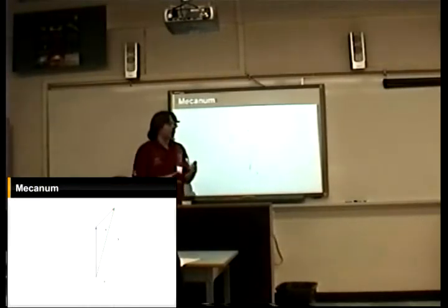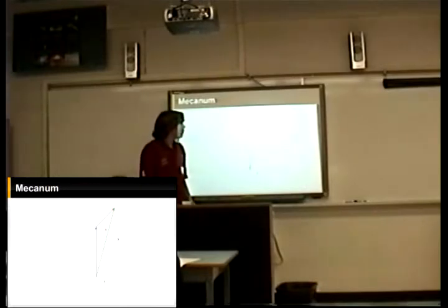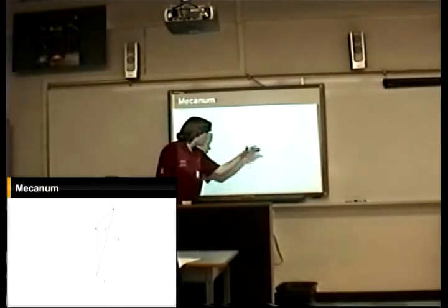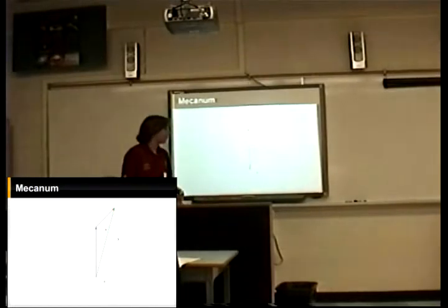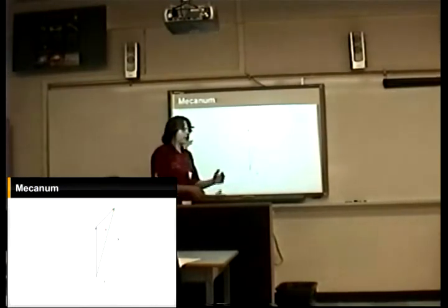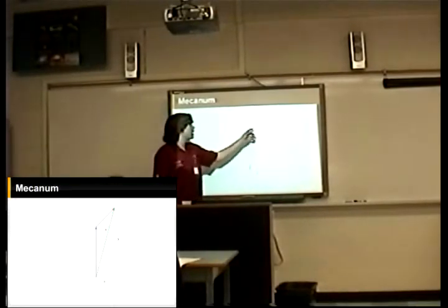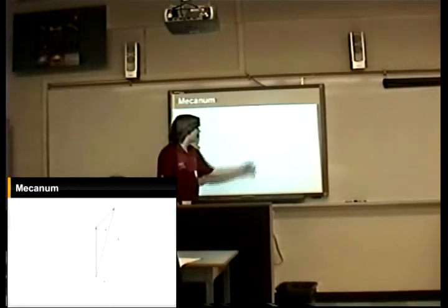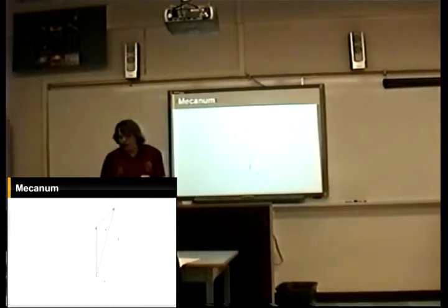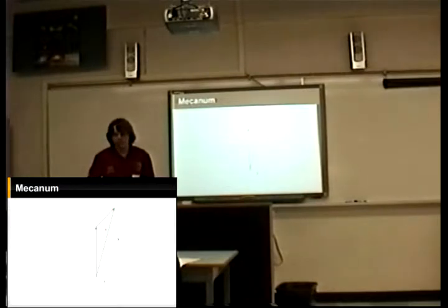And so the wheel roller rotating needs to account for the entire x-coordinate of the velocity vector. Because the wheel is oriented directly up and down, it doesn't have an x-coordinate. So the x-coordinate of the red vector is going to be equal to the x-coordinate of our green vector. And the other thing that we know about Mecanum wheels is the rollers are oriented at 45 degrees.